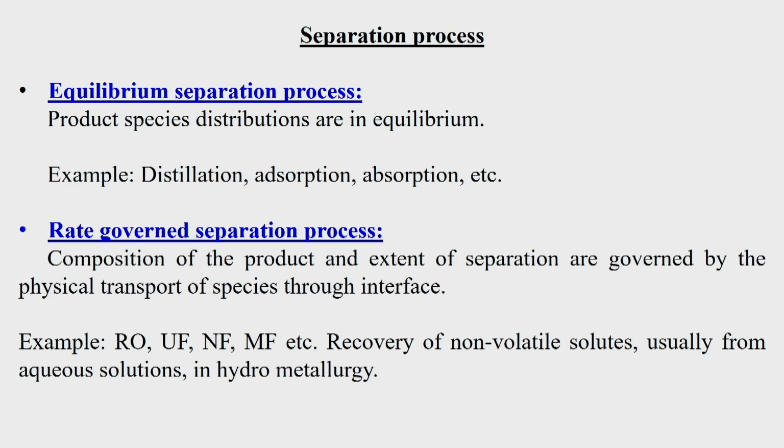Whenever we talk about membrane based separation processes, we will find that the extent of separation is controlled by either the pressure gradient, concentration gradient, or electrochemical potential gradient, and the size of the molecule to be separated by this semi permeable barrier.